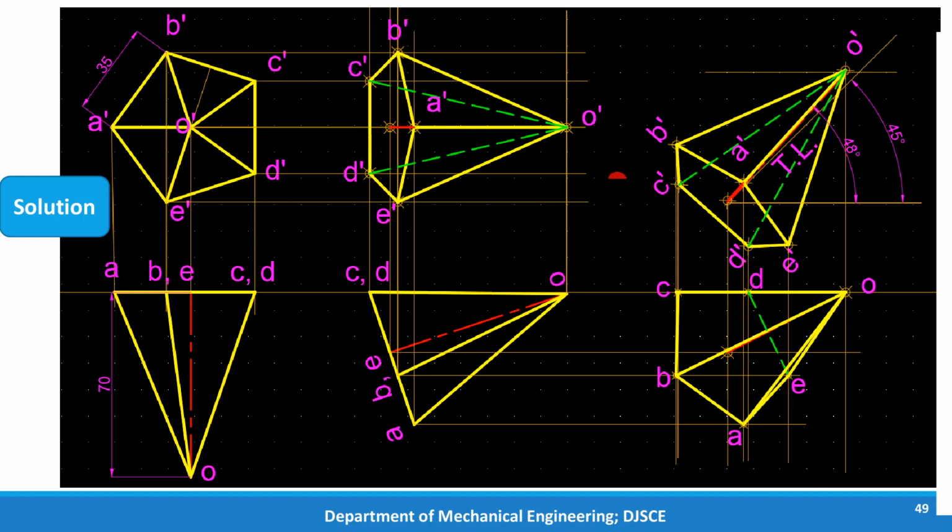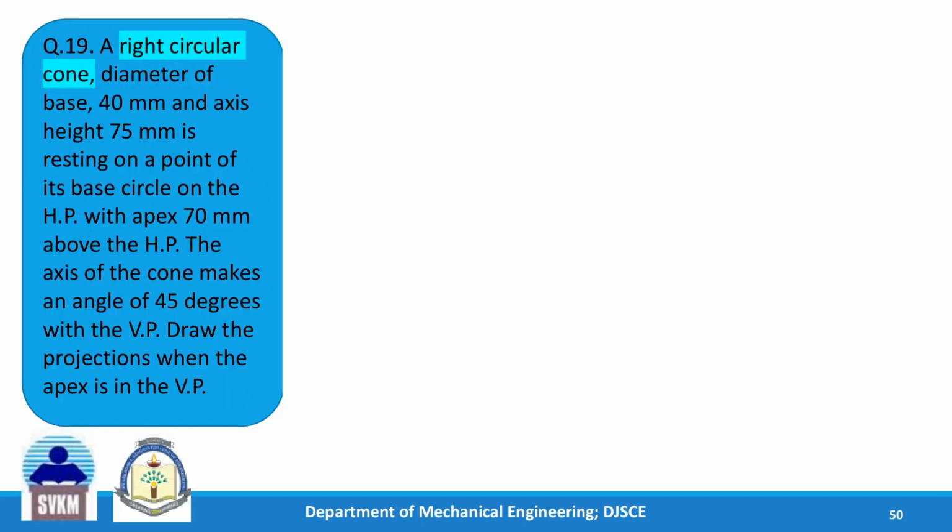So this is drawn here, and then take the projections down, take the projections horizontally and connect the edges according to the visibility. Now you have to take care that apex is nearer to the observer. Observer is here, so apex is nearer to the observer. That is correct. Now accordingly, visibility wise, we do these connections and complete this top view of the third step. And this is the last one for this session.